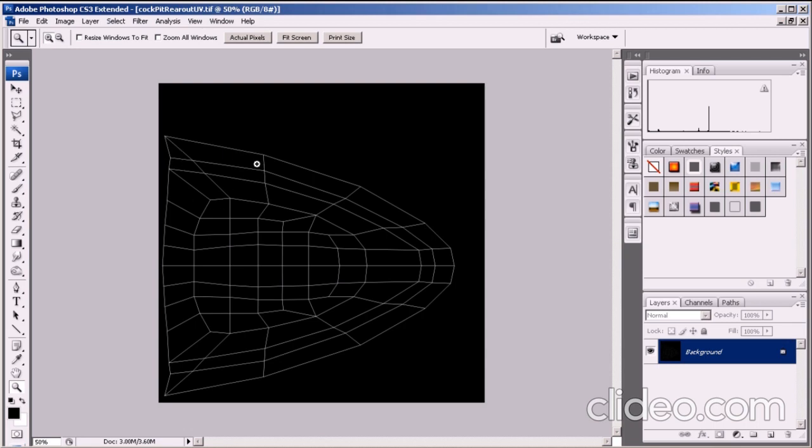If we wanted to place a specific area of detail, perhaps a specific area of bump, specularity, even transparency, we know that if we work to these guidelines or the UV layout, when we apply the texture to a material in Maya, the detail will sit exactly where we require it.